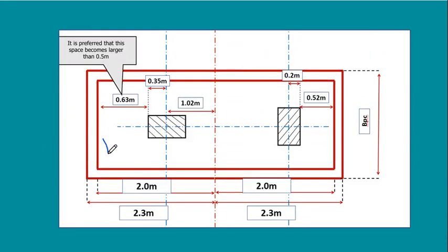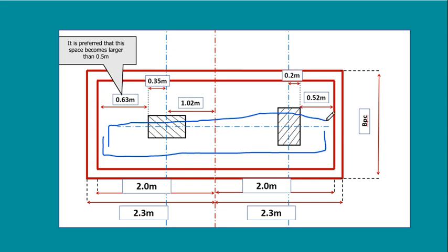I'm going to draw it a little bit better. If I have here, this is my first bar, reinforcing bar here. This is the lower one, and I have an upper one here like this. Of course, it is repeated every, say, 20 centimeters and so on. These are my reinforcement in this long direction.